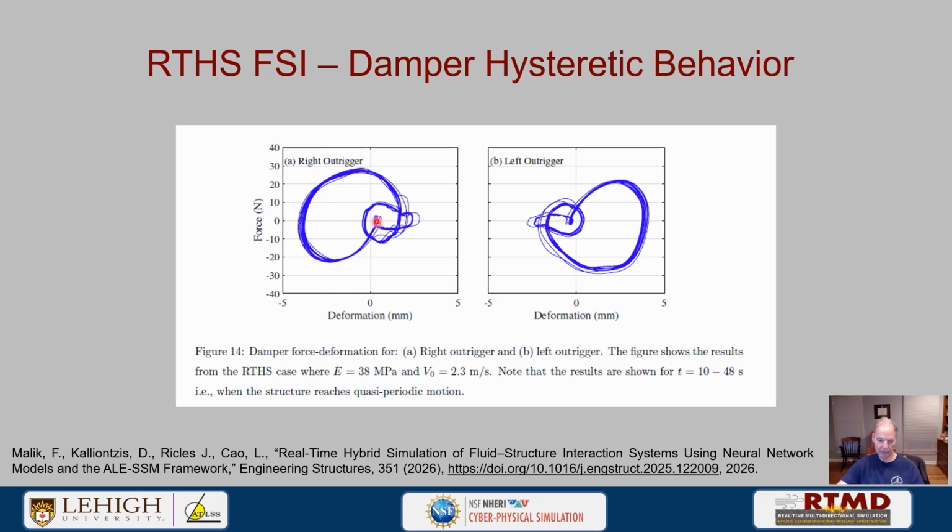But then, after 5 seconds, we have the accumulation and the deformations evolving over the time history, and it's kind of anti-symmetric because of the left outrigger and the right outrigger. There's a line of symmetry, but it's actually a line of anti-symmetry about the midpoint of the structure because the building deforms like this. This damper is in compression, this damper is in tension.